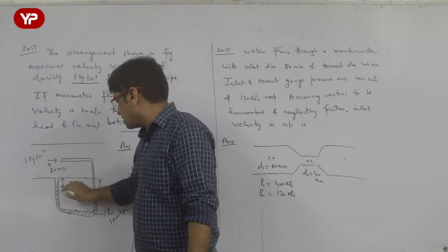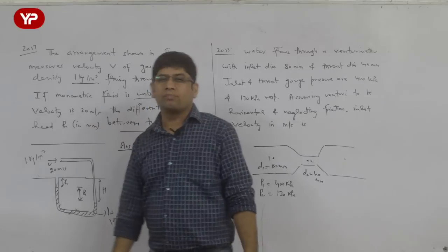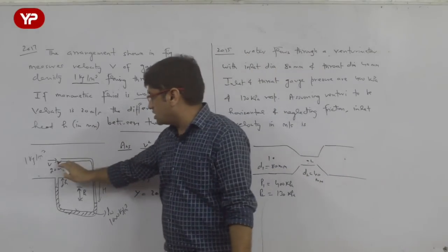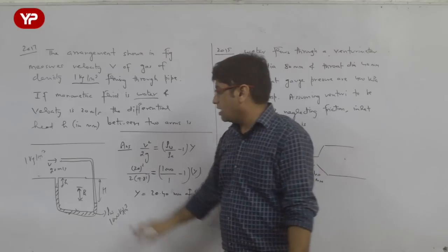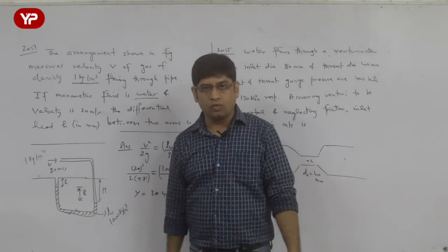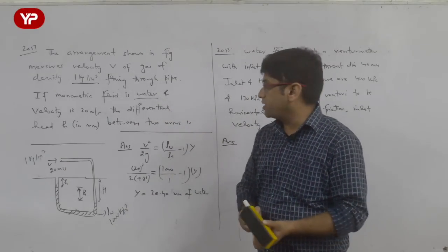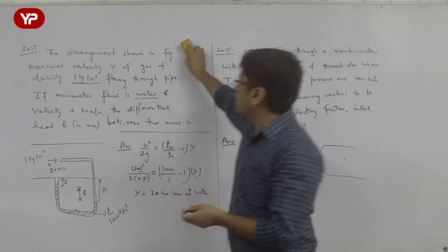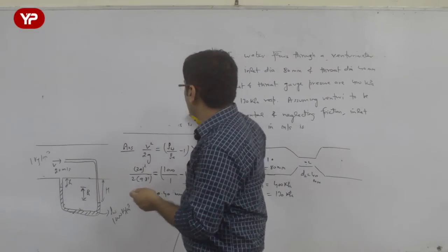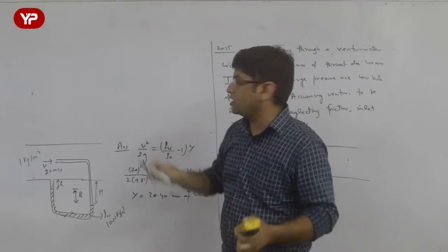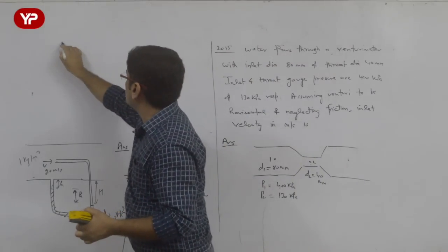This side is a static head which is small h, and that is only pressure energy. So pressure energy at this point plus kinetic energy at this point gives you stagnation head. And now we have to find out what is the velocity of flow. We know from the pitot tube, that is we have discussed pitot tube questions just now. This question is similar to the pitot tube questions. Let me give you the pitot tube questions to you.